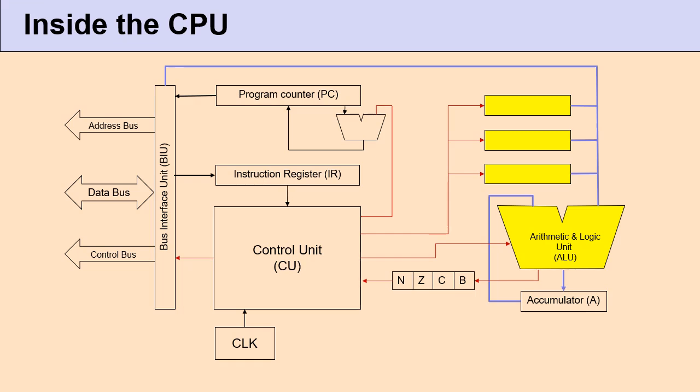Why do we need a few registers? Because it's very likely that the CPU will be doing a sequence of activities and the ALU will need multiple operations to be carried out one after the other, and the data needed for these operations can be held within the CPU without using an expensive memory read cycle for each operation.